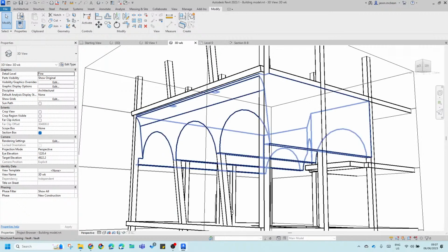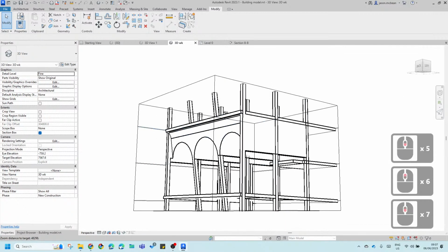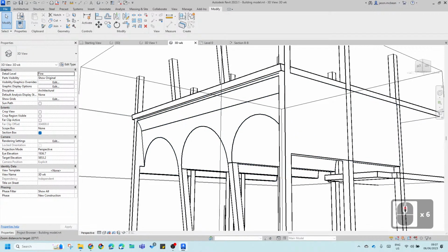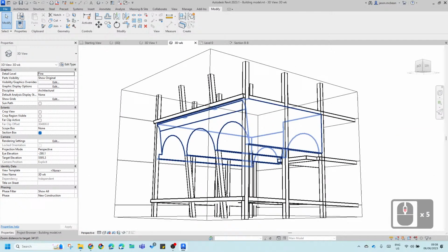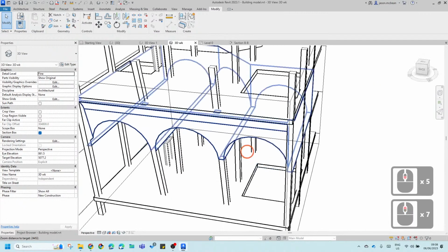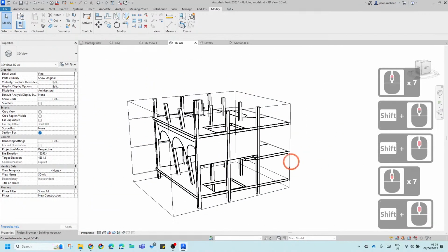Exactly. Parking decks on a shopping centre's roof: they shape polystyrene, then just put tar over it, and you can drive over it. You don't want screed, because the structure gets too heavy, so they use polystyrene and shape it so it all falls to the outlets. Very lightweight, and you put tar over it. How do I show on a drawing that this is a polystyrene structure?